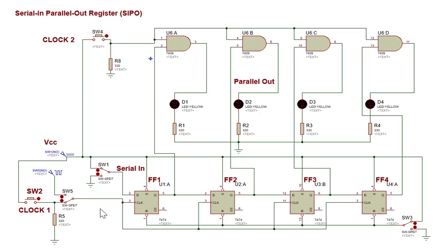The next flip-flop 2 gets its input from the output of the first flip-flop 1, so whatever output of flip-flop 1 is will be transferred to flip-flop 2 at the next clock signal. The same condition will happen to flip-flop 3 and flip-flop 4, since the output of the previous flip-flop becomes the input of the next one.